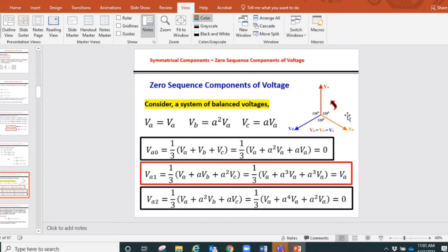Okay, you can choose it, but our normal convention is to choose the anti-clockwise direction. Okay, so we can now move. I'm considering these phasors, the voltages VA, VB, VC on the diagram with a sequence of A, B, C as shown with the direction of rotation and the magnitudes, the balanced voltages. The magnitudes VA, VB, VC are equal to each other. They are displaced from each other by 120 degrees.